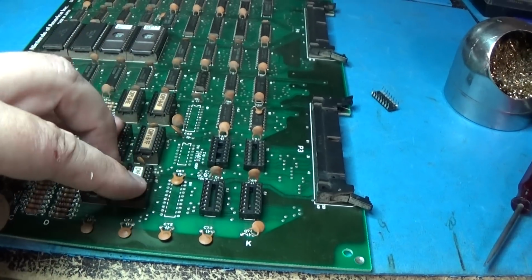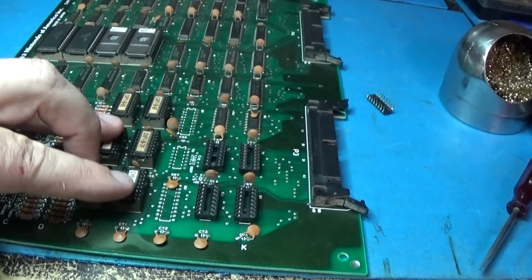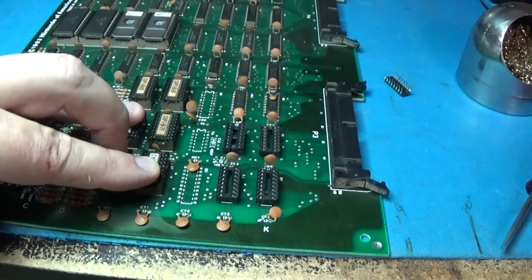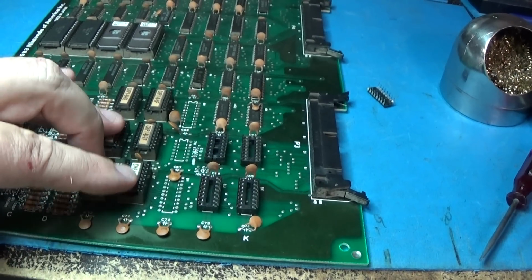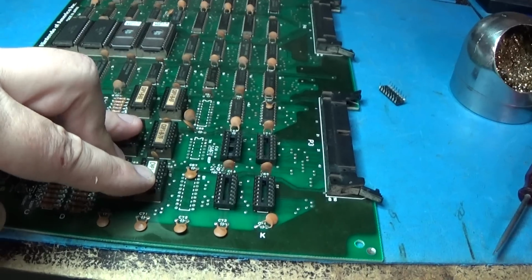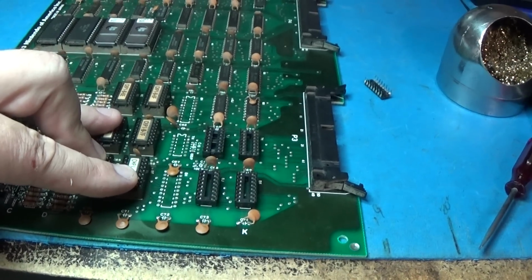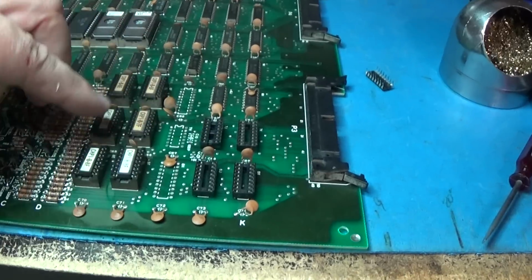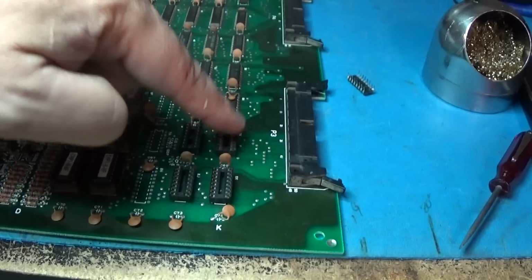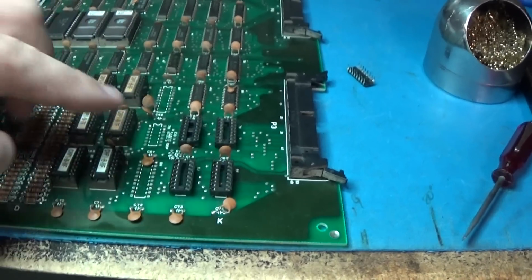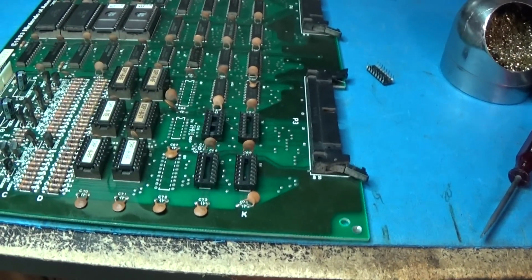These are the bottom monitor red, green, and blue PROM chips. I'm figuring these are good. These are actual Punch-Out verified PROMs. So what I'm going to do is inverse the addressing to them by putting 353s in the board and see if that fixes my problem.